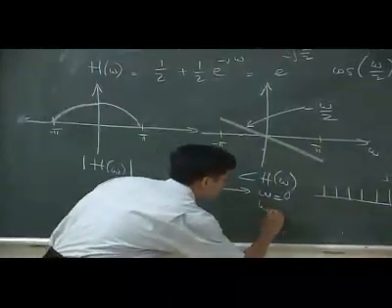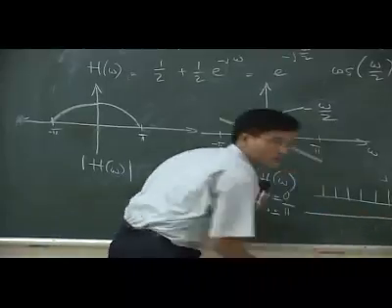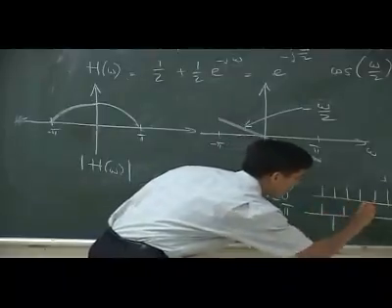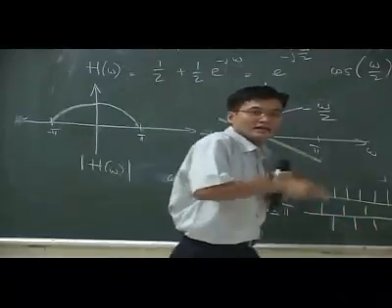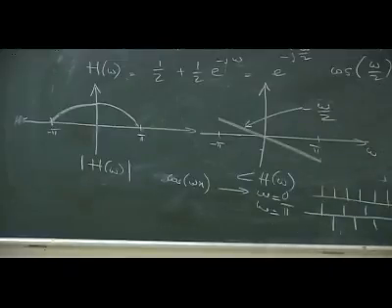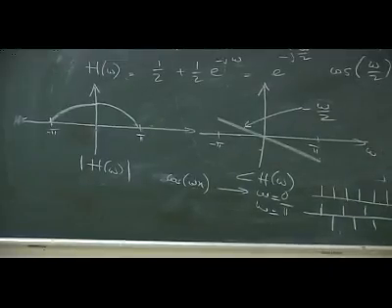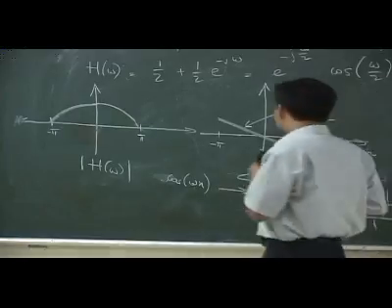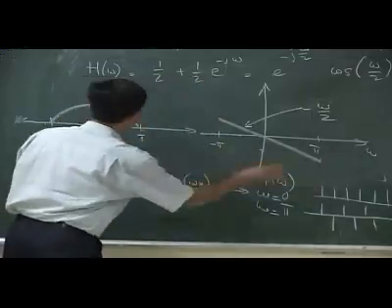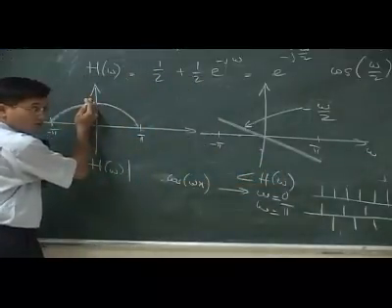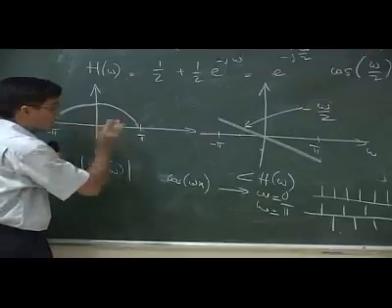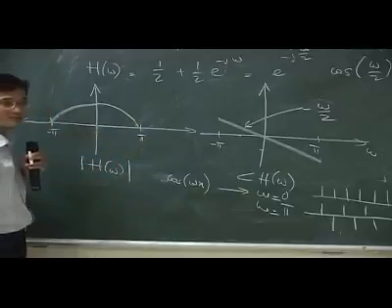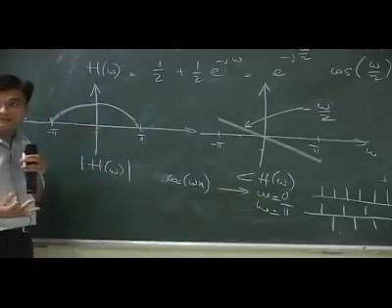When omega equal to pi, what would that signal be? Boom, boom, boom, right? Such as 1, minus 1, 1, minus 1. So something oscillates extremely fast. That is a high frequency. Where this thing here, it's a constant, very smooth signal. So what it's saying here is the signal coming in, the component that is smooth gets to go through, where this kind of component gets filtered out. Right? Is that clear now?